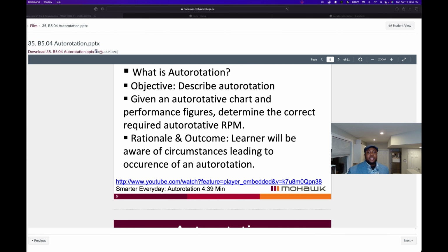The process of producing this lift with the rotor blades as they freely rotate, freewheeling from air that's flowing up through the rotor system, is what we describe as autorotation. So if you recall, when we talked before, we said during powered flight, the helicopter blades allow air to be sucked down through.